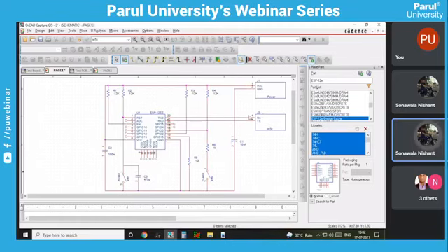So at the end, when we practically implement this, you can easily understand how we have implemented J1 and J2. This is the first step you have to do before designing a PCB: the schematic should be ready, and all the components should be ready. Before designing, you have to prepare things like the controller. You have to choose what size of controller you require, what through hole components you require on your PCB, and what SMD components you require on your PCB.